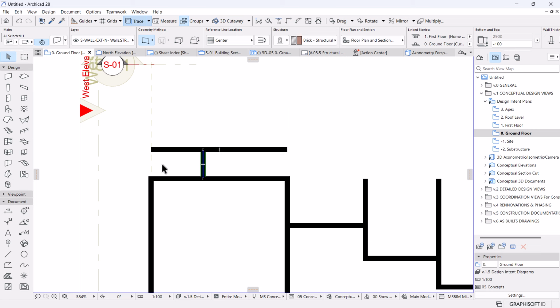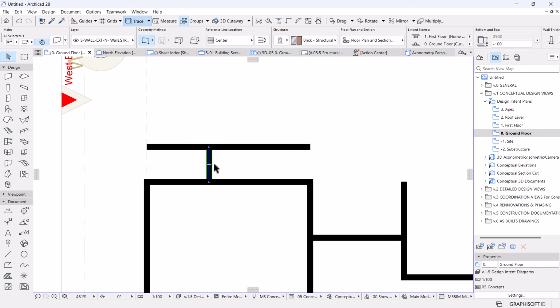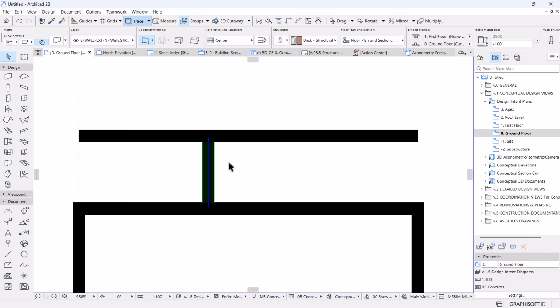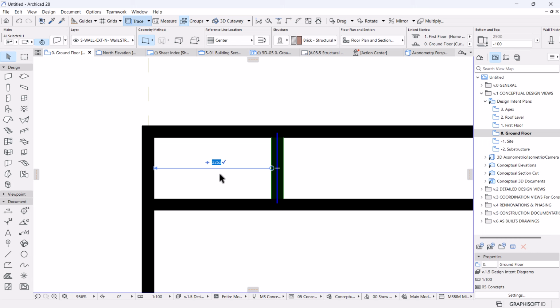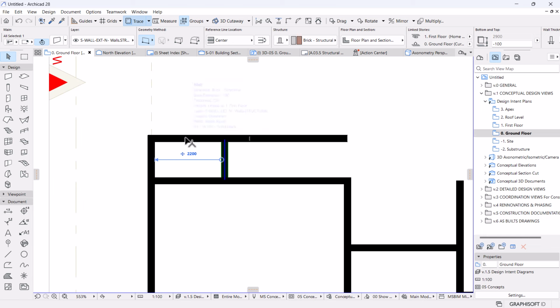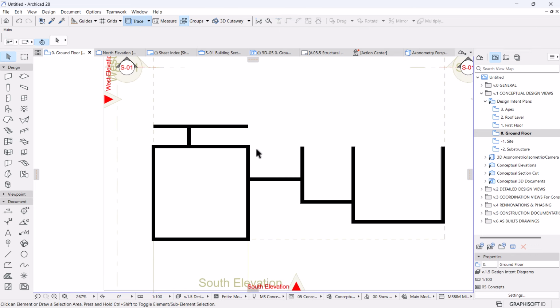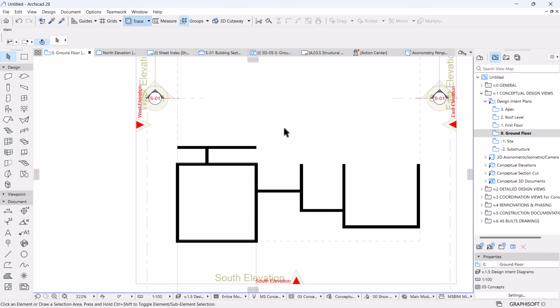So let's select it. We need to determine the distance. I don't know why the guides are not showing for this. Let me just do this for now and see. Oh yeah, okay, I'm going to offset it from here by 2.2. This is critical in making sure that you are getting the precise measurements for your spaces, positioning of elements, like that. So the distance guides were a game changer in ArchiCAD. It revolutionized the way we work, setting up the position of the elements, the spaces, dimensions. And previously with other versions it was really a headache to address this kind of exercise.